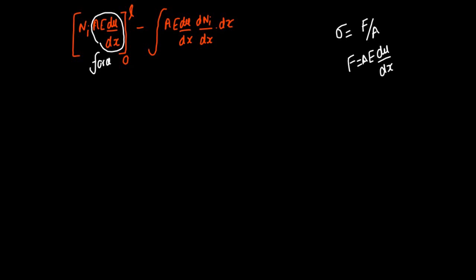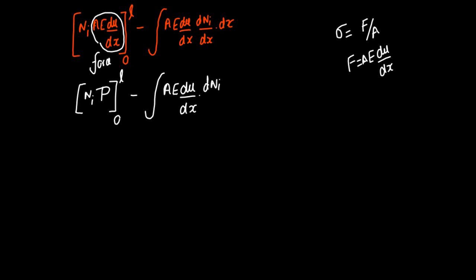I can say it's simply Ni into the force, which I can call capital P, the point load, over the limit 0 to L, minus the integral of AE into du over dx into dNi over dx into dx.